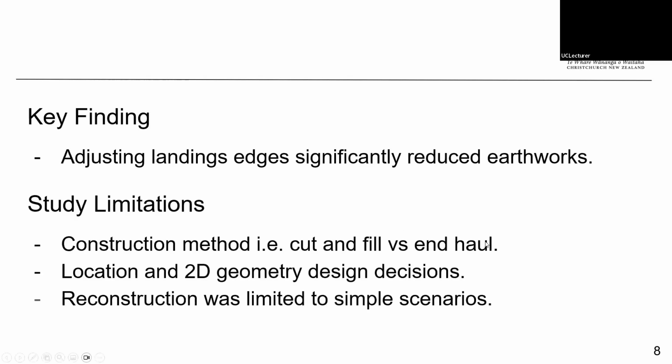Now, although these results were promising there were a number of limitations to the approach that need to be discussed. The first of which was that it wasn't possible to infer the construction method that the contractor had used from the digital elevation model. This meant that I could have been comparing landings that I'd designed using cut and fill to landings that have been constructed using end haul.